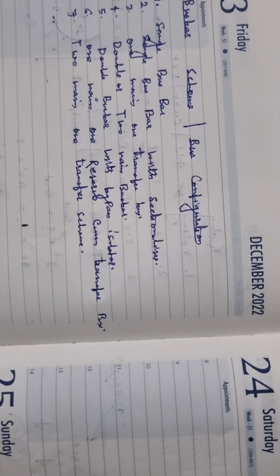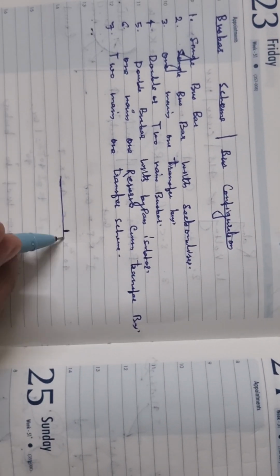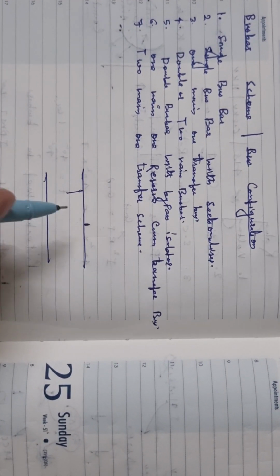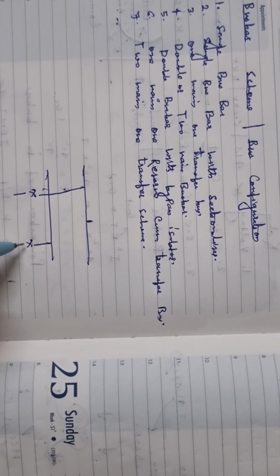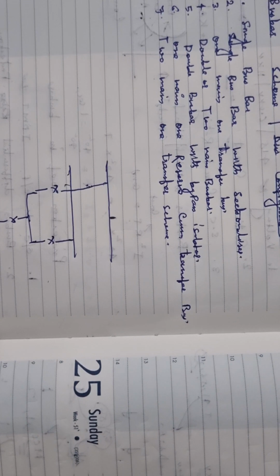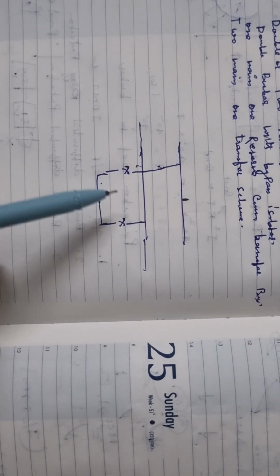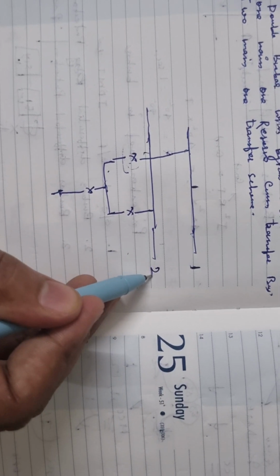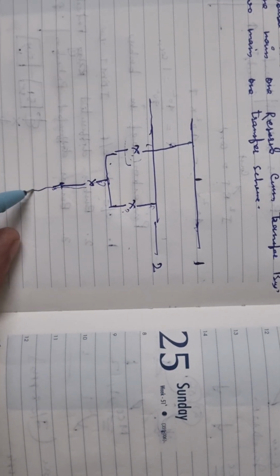Now I will show you a diagram, for example, a double bus bar. How does it look? As its name says, double bus bar means two bus bars will be there. In this bus bar, we have connectivity like this. We have one isolator which we can connect to bus bar 1, and take this as bus bar 2, and we can connect through this isolator to this, and a single breaker will go to the outgoing source.